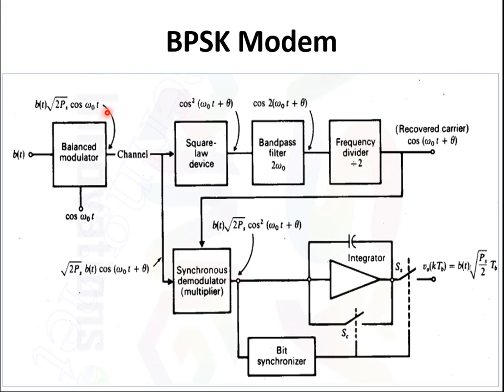This is the equation for your BPSK modulated wave. Sometimes you are supposed to write such things also: what will be the mathematical expression for a BPSK modulated waveform? This is the mathematical expression. This will be sent to two blocks. One is the carrier reconstruction circuitry, so this complete upper part is my carrier reconstruction circuitry, and this lower one, like I said, is the phase demodulator or synchronous demodulator.